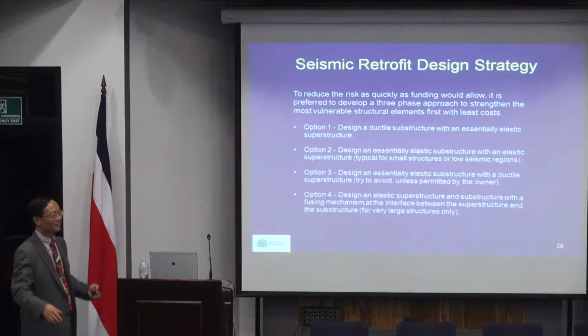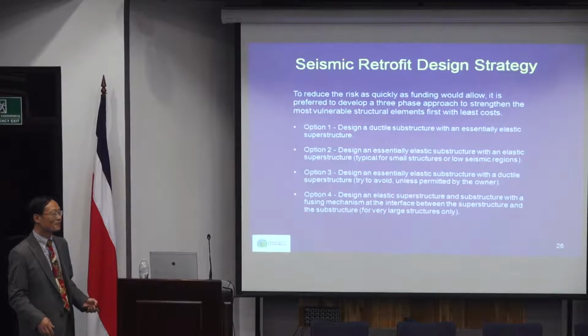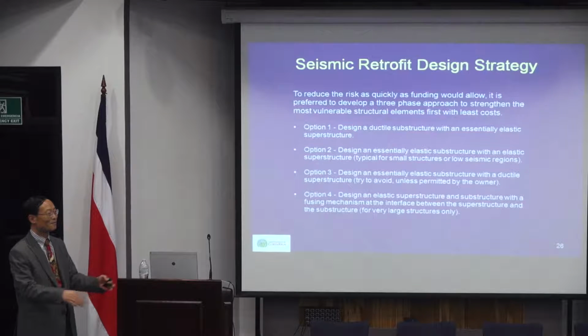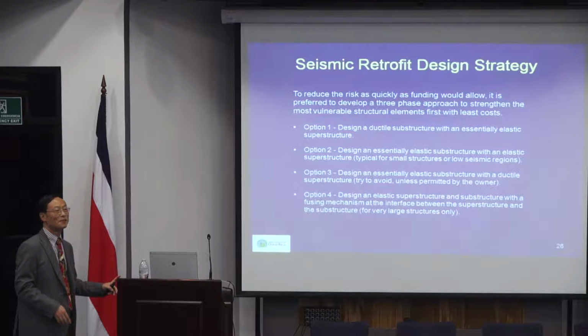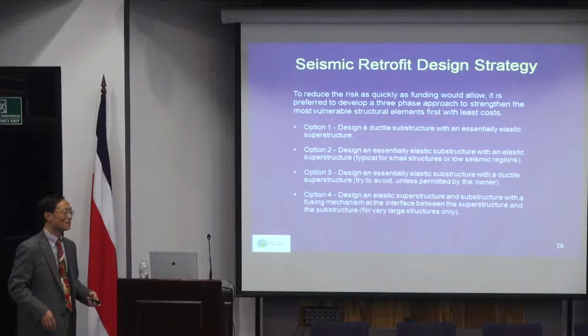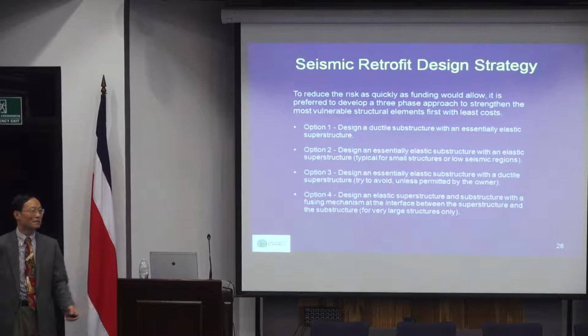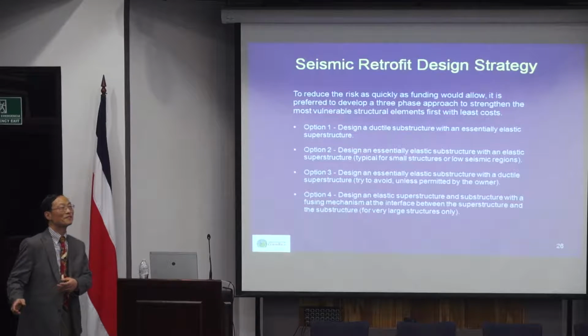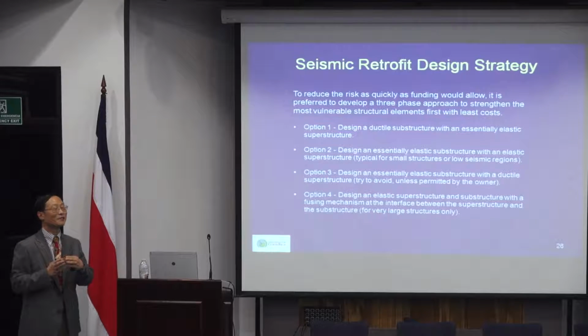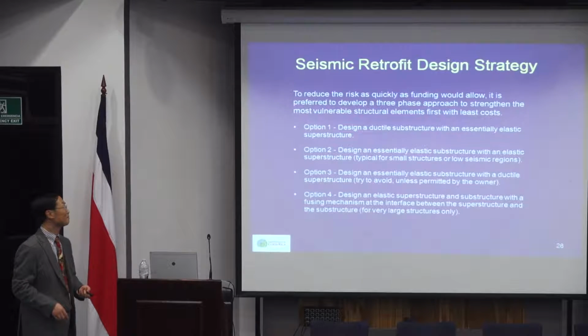And the same thing, when you do a rehab, you always have problems with expansion joints. And when designing a new bridge, you say, why do I need expansion joints? Can I just make them continuous? Even at the abutment, now a lot of people use an integral abutment, integral with the superstructure, so you don't need any expansion joints.